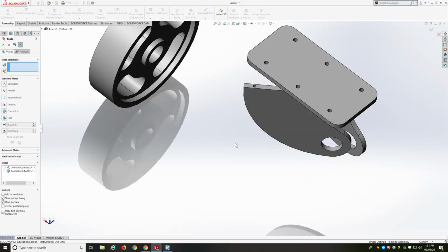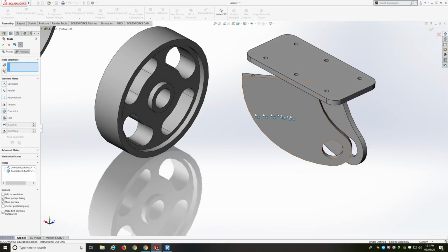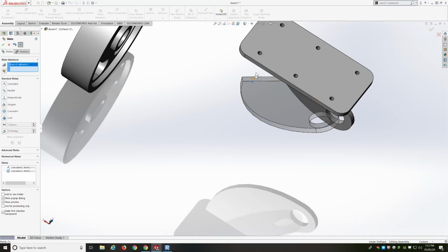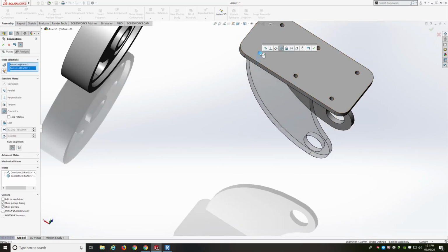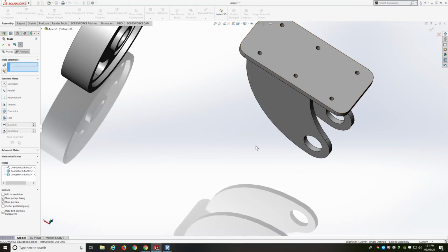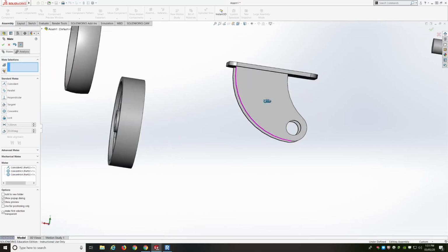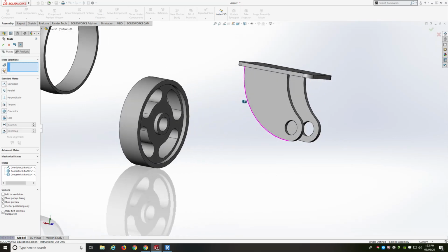I know a lot of students say, oh, this side plate is close now, but then this is close as well, so I'm going to kind of swap back and forth. Do one part at a time and get everything fully constrained. Left click, left click. It satisfies the concentric mate and green check. So that part looks good so far.